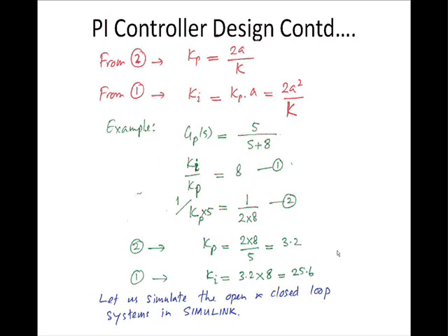And now what I am going to do is quickly construct this complete system in Simulink, and I'll show you what will be the output response of the open loop system for a unit step, what is going to be the output response for a step input in the closed loop system, and then we can compare how the closed loop system response is going to be much improved compared to the open loop process.